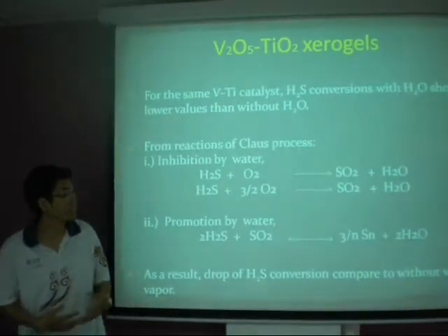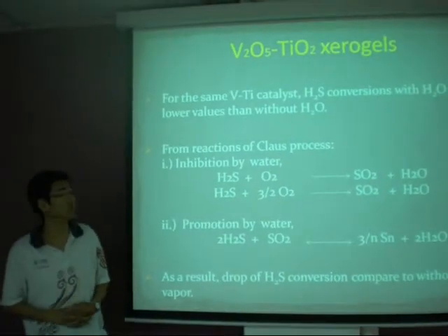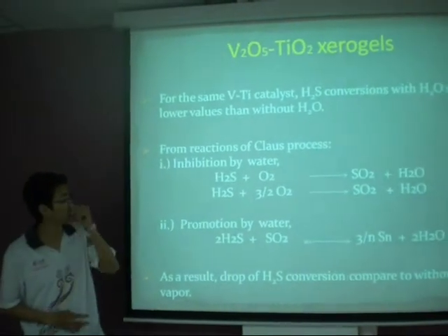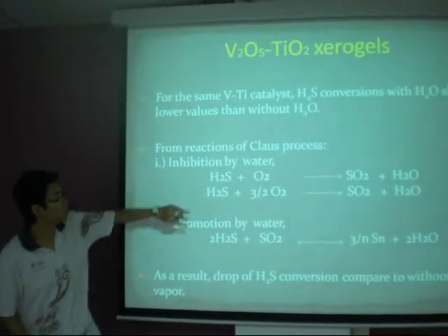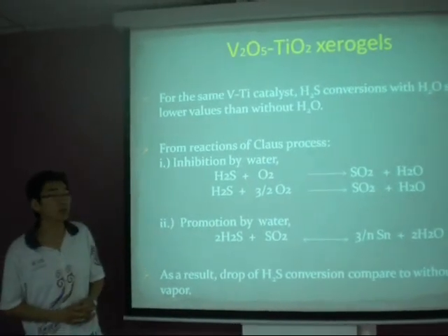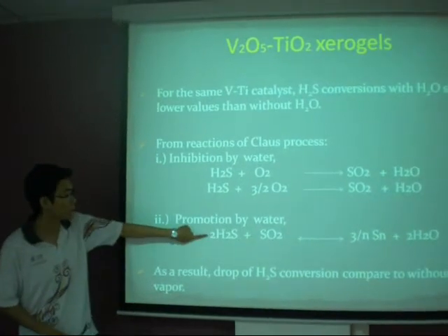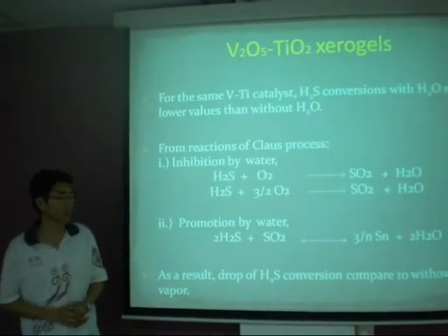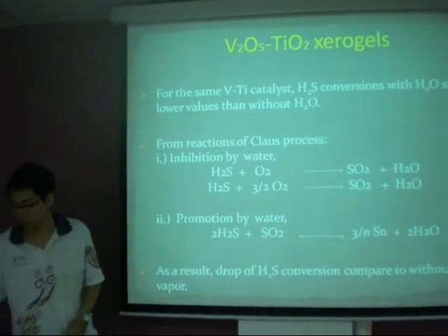In order to investigate the reason behind this, we need to understand the elementary reactions occurring in the Claus process. As you can see from the slide, the presence of water inhibits these two forward reactions. However, the presence of water can promote the reversible reaction of this one. The total effect will be a drop in hydrogen sulfide conversion.